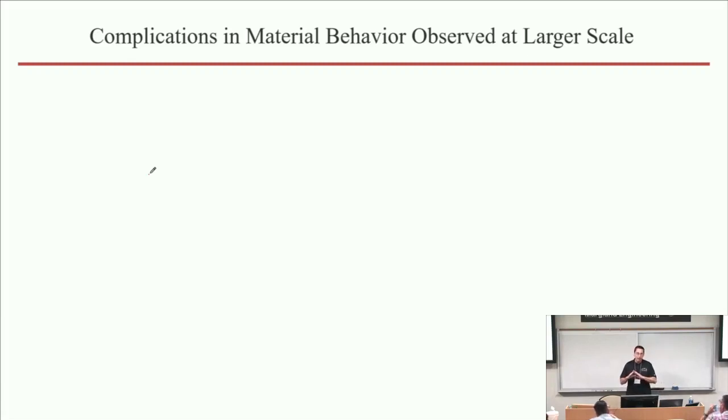Now, that's a very broad statement, and there are very many examples of it in the literature where people do bench-scale measurements of various properties of the combustible material and then try to produce a full-scale simulation of fire growth on a wall, and find out that there are things that do not show up at all in the test that suddenly become prominent features of the large-scale experiments.